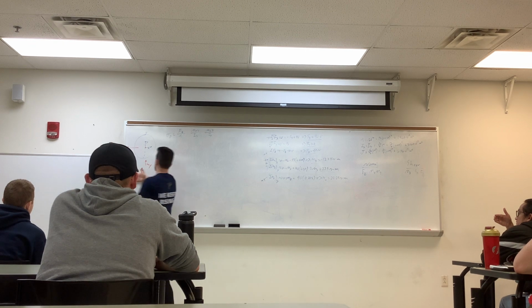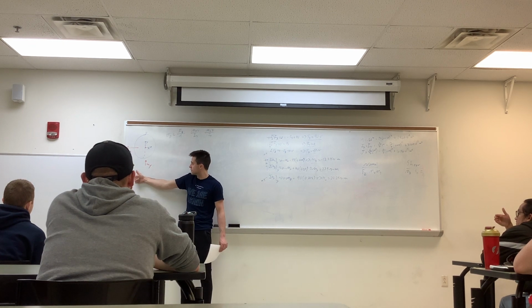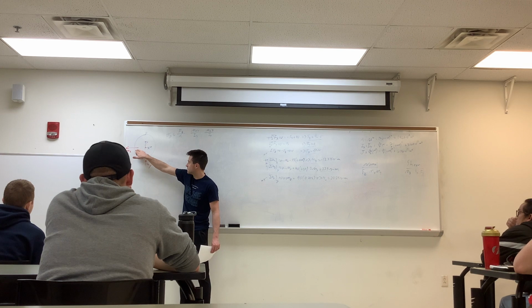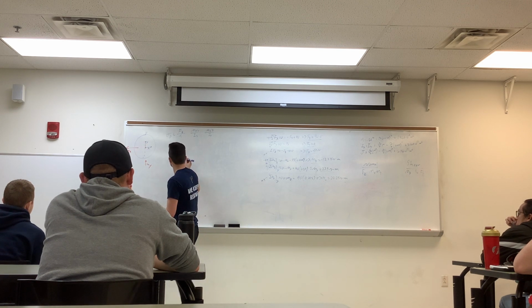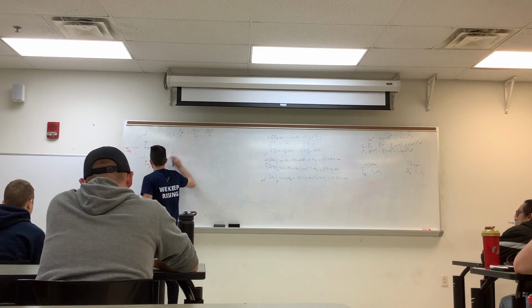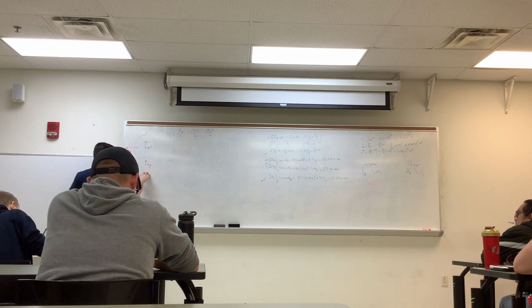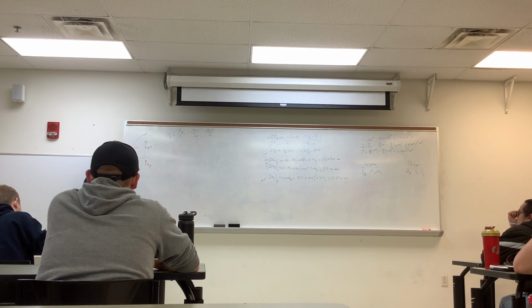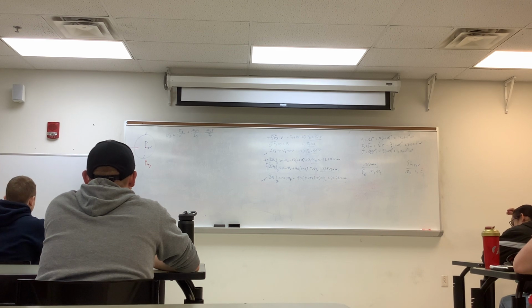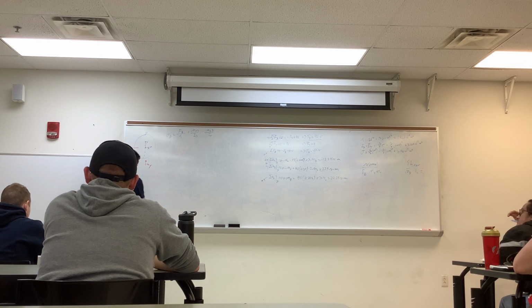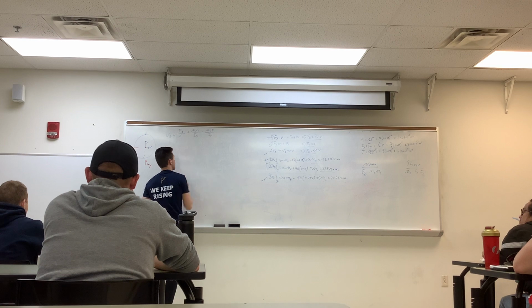We're using the right-hand rule here: thumb along that axis, curling our fingers, looking at what's happening to the left of this, giving us positive. So positive on x. Similarly, moment about y, same deal. It's acting below, so we will have this direction as negative.